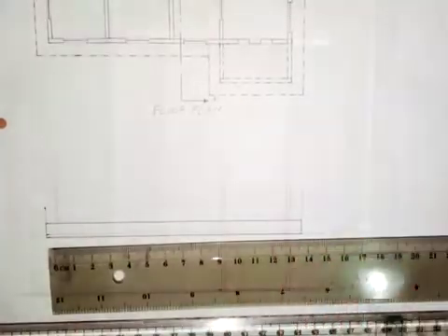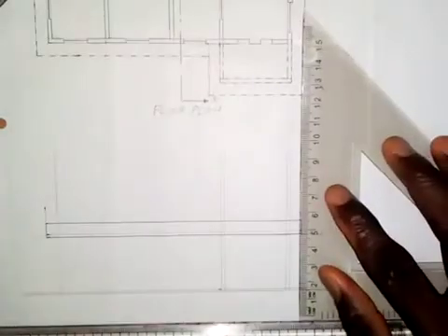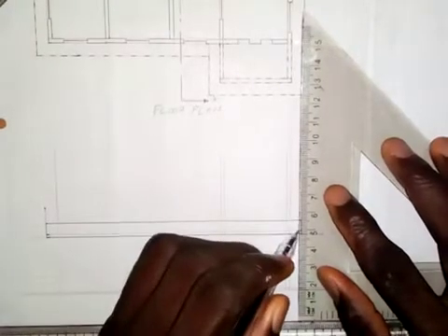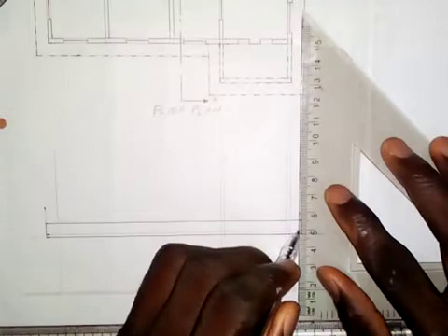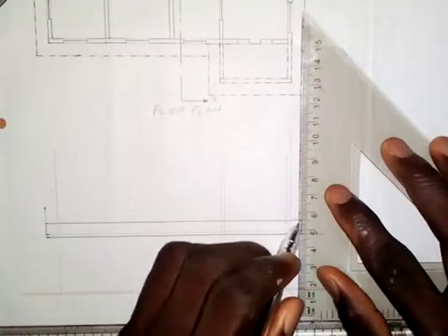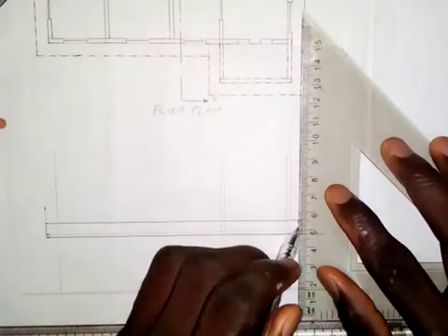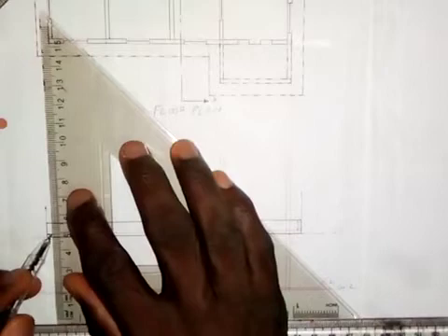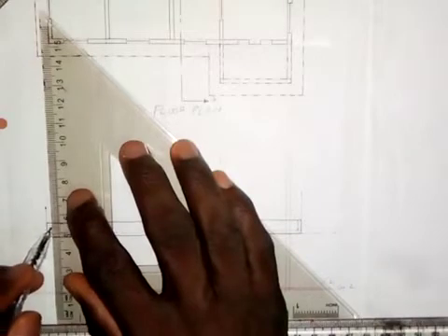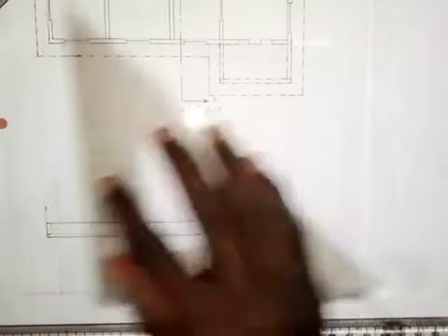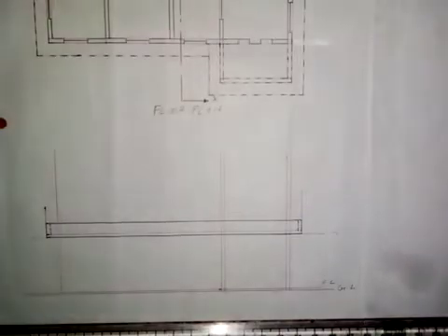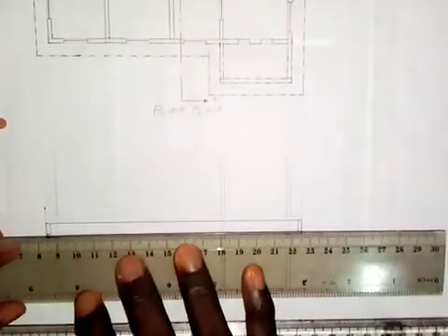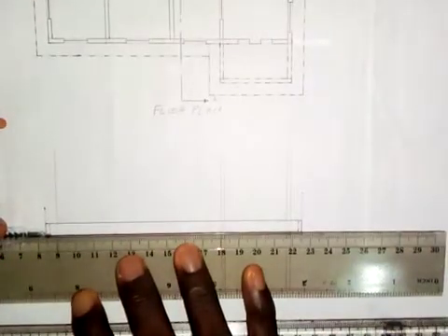So then I'm going to draw a vertical line. So this will be a vertical short dashes line. Here also I will draw a vertical short dashes line. That is the part that is hidden from us. So this line here, I will also draw as a short dashes line.